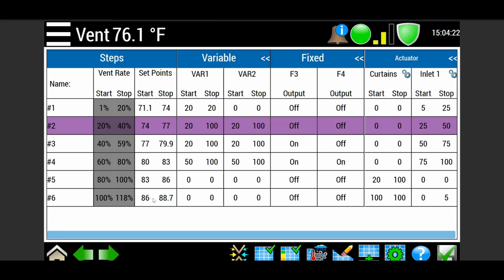So in the end, to save yourself time, to make sure that you're not having to redo your set points, figure out from the start, what is your start temperature? What is your stop temperature going to be so that you know that start temperature and bandwidth value? And then how many steps are you going to use? That way you can set it up once, set it up correctly, don't have to redo any work.